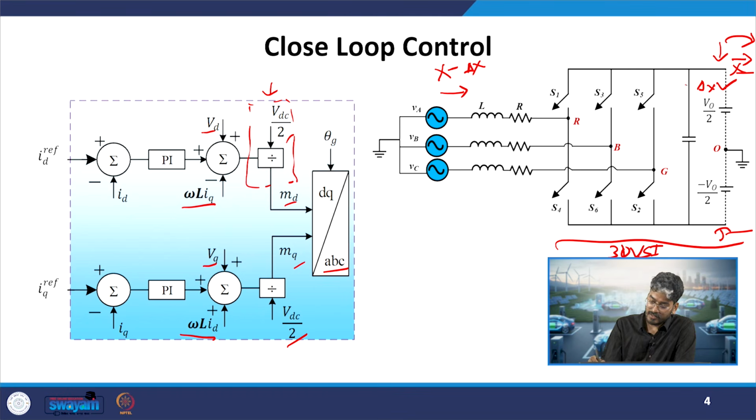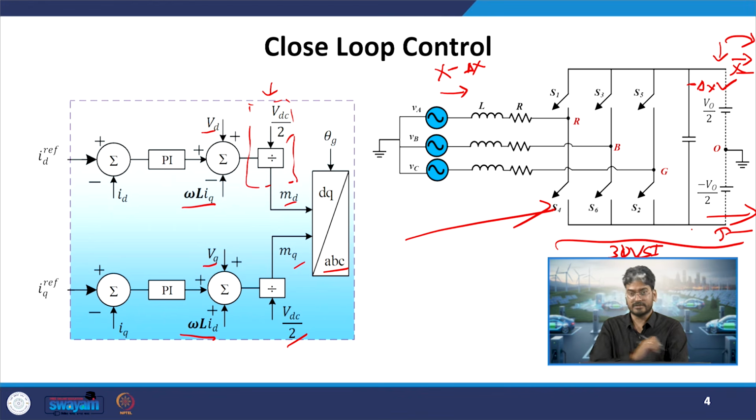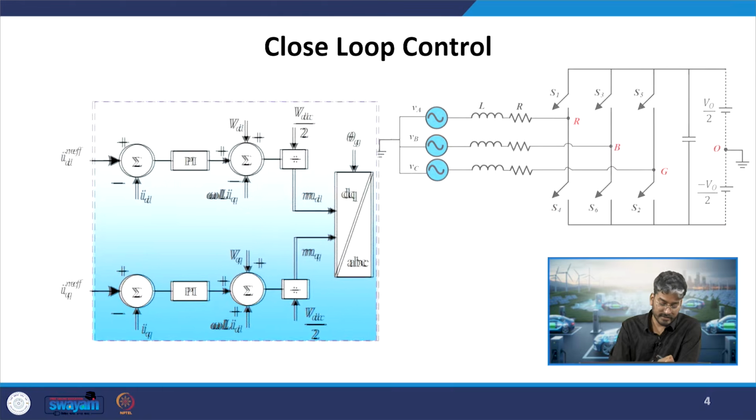So, here now what will happen? This negative delta X, or the deficit of current, will be supplied by the capacitor. What is the meaning of minus delta X? The capacitor is behaving as a source and ultimately it will get discharged. If I am maintaining this VDC, what is the meaning of that? Whichever power is coming from the preceding stage is given to the follower stage. Whichever power is drawn at the front end is being given to the load, neglecting the losses in this analysis.